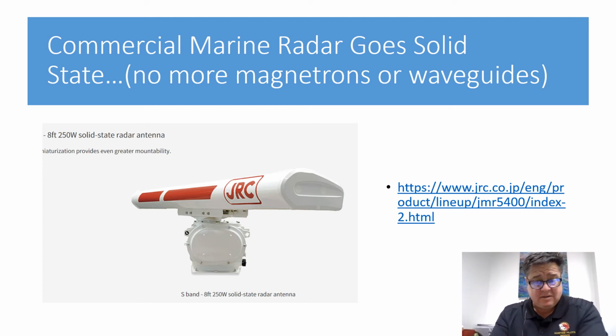The nice thing is that you'll have no 8 to 12,000 hour limitation, and you'll have no degradation of the radar picture over time with a solid state system. And it uses a lot less electricity because you don't have to heat up this big block of metal and throw a bunch of electricity into it and make it hum like we talked about before. You don't have to do all that. You just use a regular computer, basically, and the computer has a fancy board in it that makes a radar signal on the board using a solid state technology.